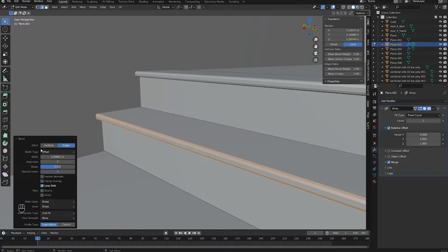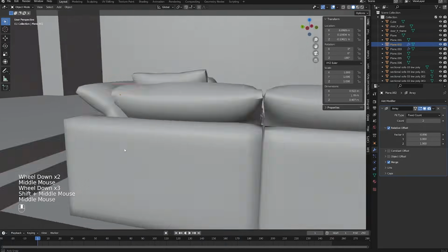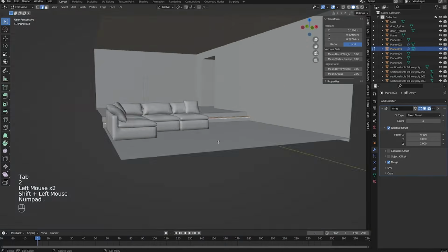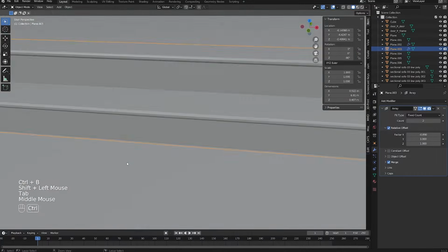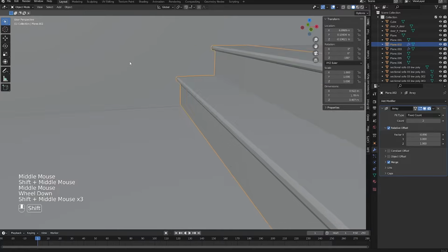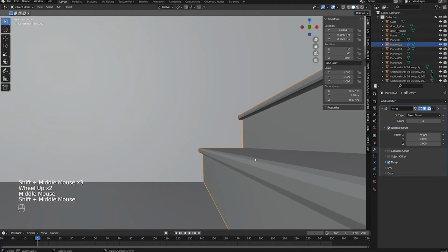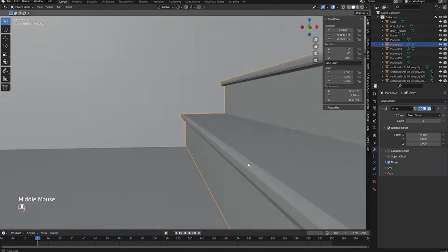After we use the bevel tool, before we click off of anything, we get a bunch of options down here that we can play with if we wanted to, but the default settings are more than good enough for me. Let's do the same thing to this one. Select that edge, select this edge, Control B. Perfect. One thing I don't like is how you can see each edge, or each face, it's quite sharp.